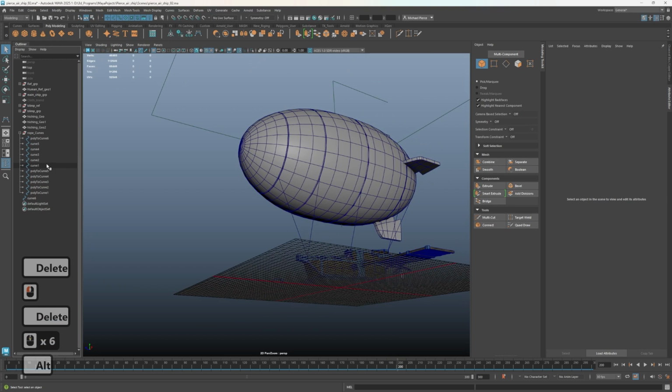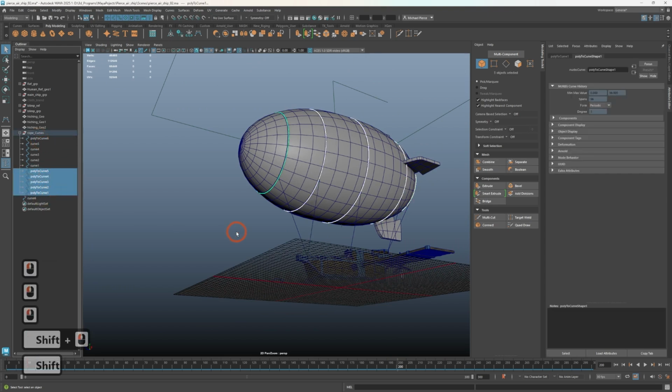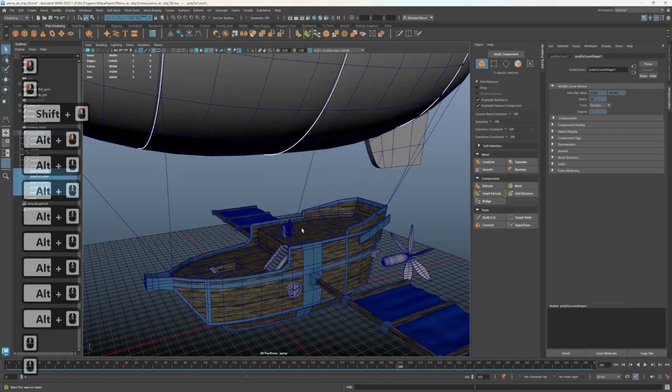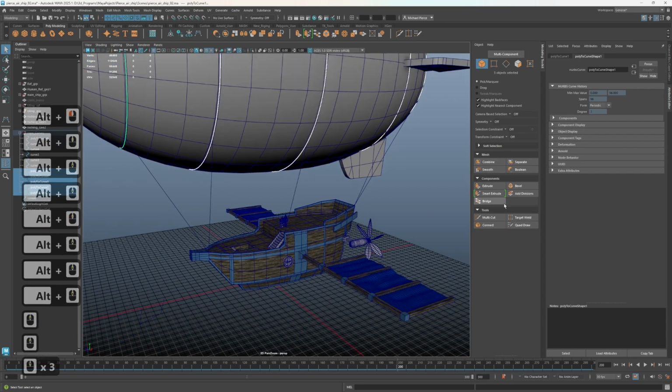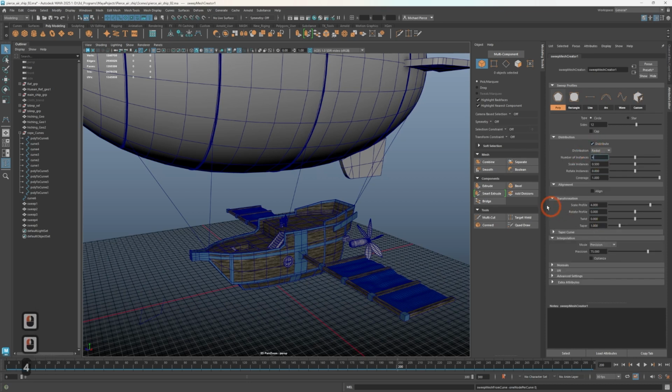Then I'm going to grab the curves, poly 2 curves, because I know these ones are. Making sure that I only grab those ones, and then I'm going to sweep them separate. So these I can do 12, and I might even just take this up to 4, making the rope a lot thicker. And then I can do this with 4.7, and then I can do a twist of, I'm going to say 100, to see what it looks like.